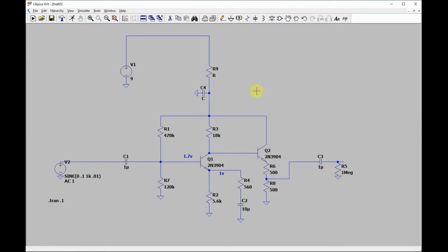What happens is, say you have a bunch of different areas in your circuit where you have amplification occurring and so forth. Some of that starts feeding back or getting into the rails, like the power supply system, and somehow it gets back to the amplifier. If something that's being amplified gets back this way and then creeps down this way and hits the base and then gets amplified again, you get these big feedback circuits where you can get these oscillations that just happen out of nowhere.